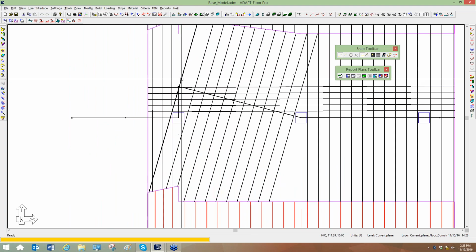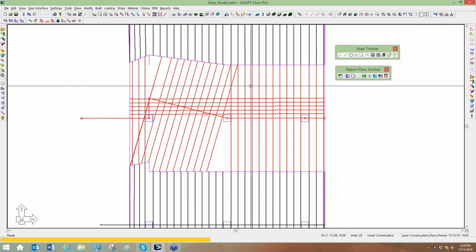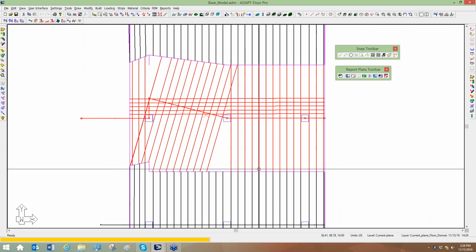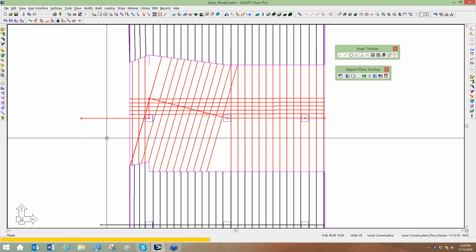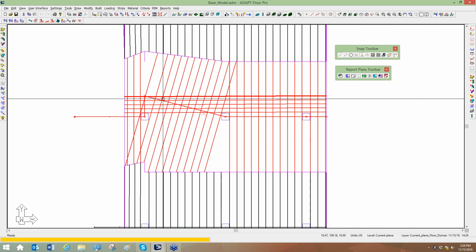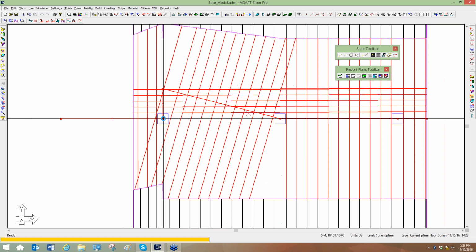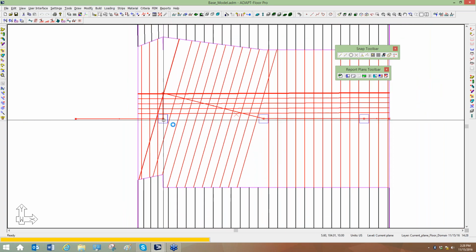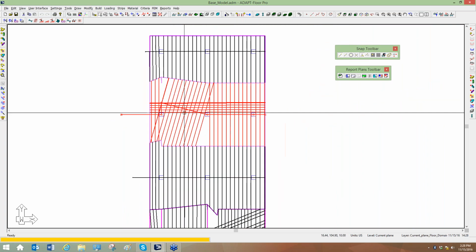There it is. You can see right here, this is an X direction support line, so all of the cuts are made in the Y direction. So we're actually looking at bending. The primary bending direction here is about the Y-axis, but because I turn this up, these cuts are actually cut in the X direction. So along an X direction support line, where we're primarily concerned with Y-axis bending, you actually have a situation where you're looking at X-axis bending. So this is not good. You don't want conditions that look like this in your support lines.